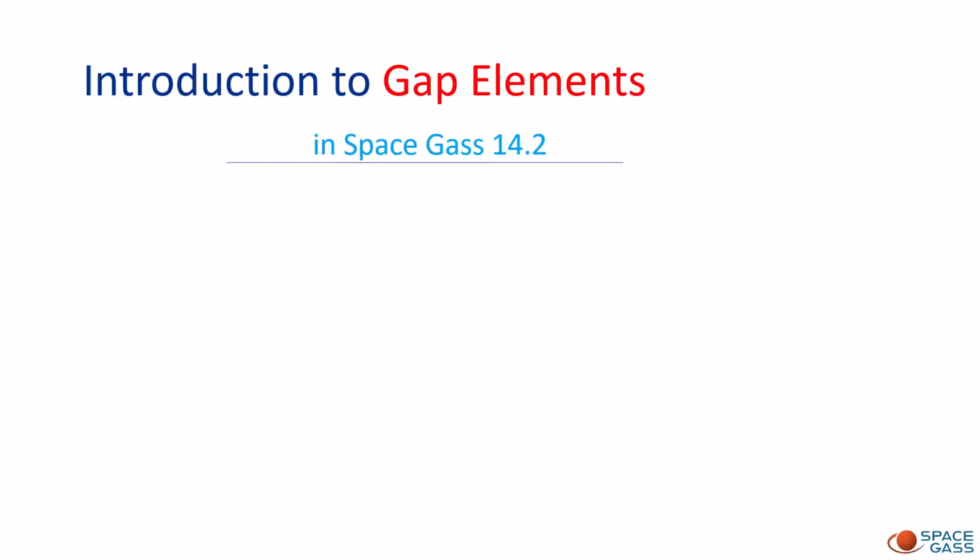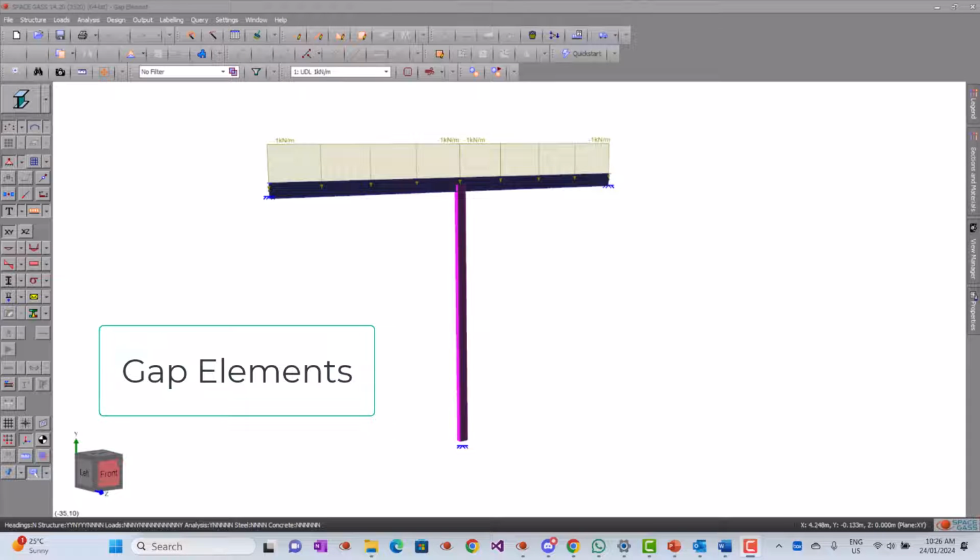In this tutorial, we'll guide you through the gap element, one of the new features introduced in Space Gas 14.2. Gap elements are defined by a tension and/or compression gap which must be taken up before any axial force is developed in the member.